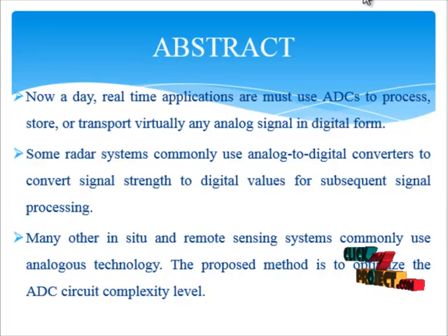The main challenge of an IF sampling ADC is linearity distortion at high input frequencies. The SFDR is of great importance in wireless communication, to support detecting weak signals and peak signals. The ADC's SFDR is restricted by the front-end sample-and-hold, and its non-linearity is transferred to the final digital output.